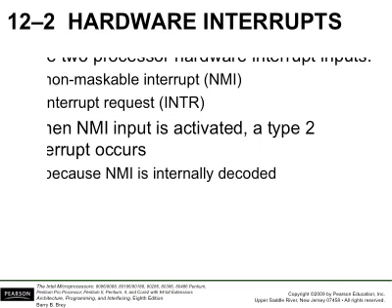Once you have a power outage, UPS will kick in, so your system can continue to operate for a certain time. But you do want a mechanism to tell the microprocessor system that if you do not save your work somewhere, chances are in the near future you're going to completely lose power.